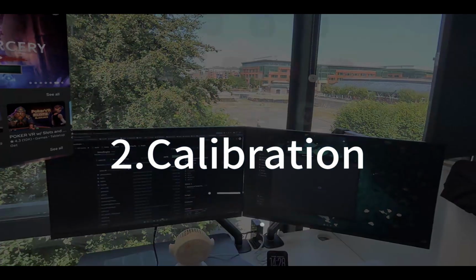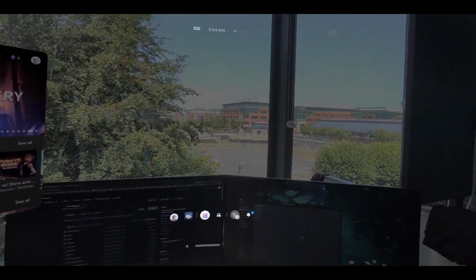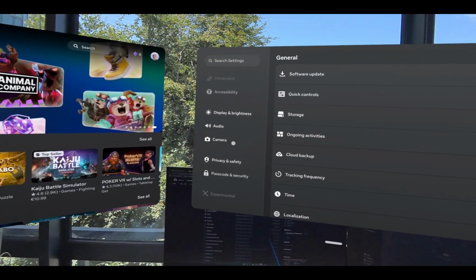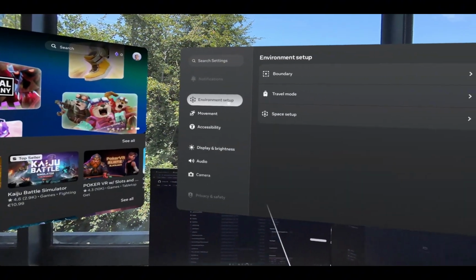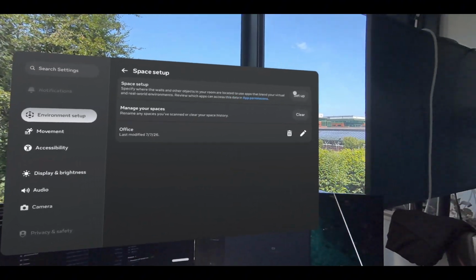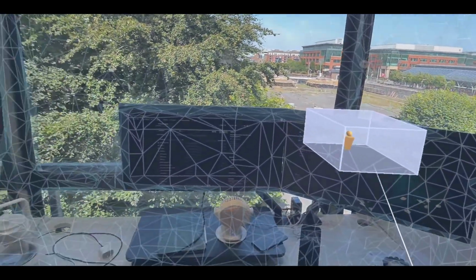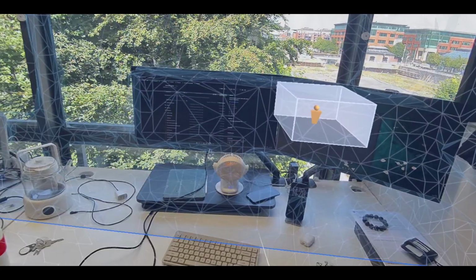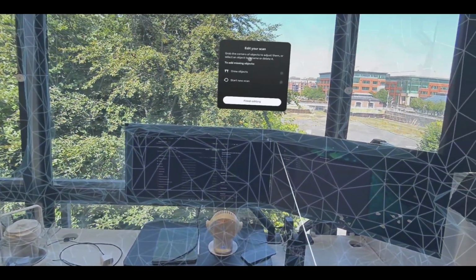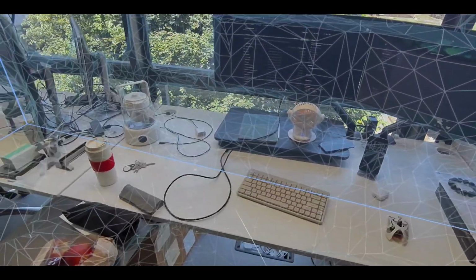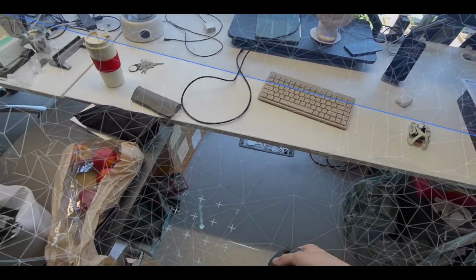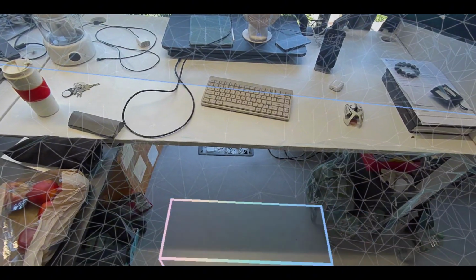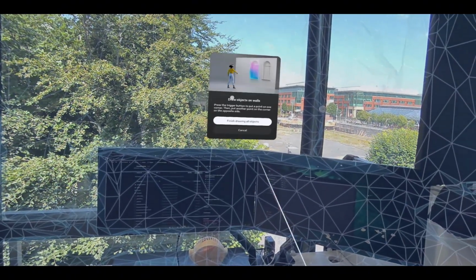After successfully launching the PC application through nDisplay, we can begin the HMD calibration. First, open Settings and go to Space Setup. Scan the current environment and then delete any automatically detected objects labeled Screen, because we will outline the screens manually. Select Draw Objects. Follow these steps to draw an approximate outline for each physical screen. Make sure that every object is assigned the screen label.